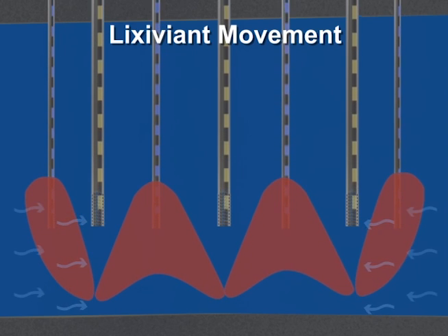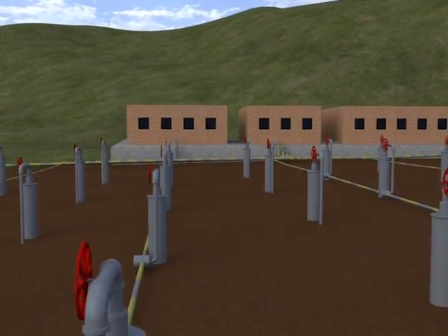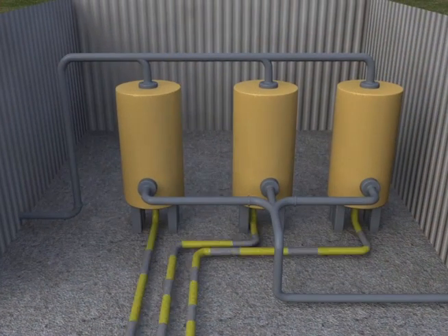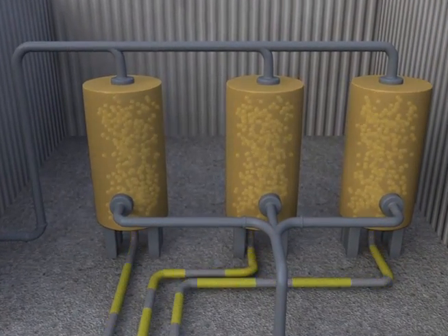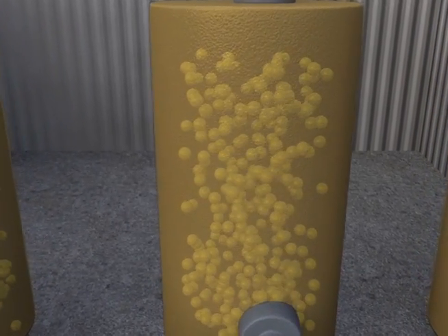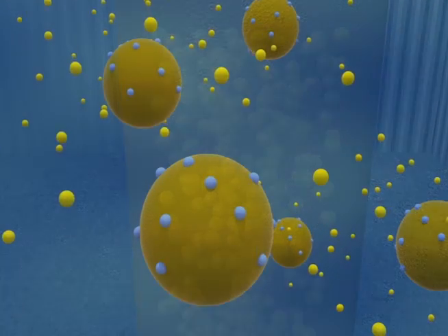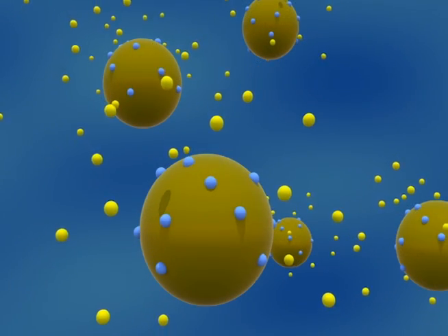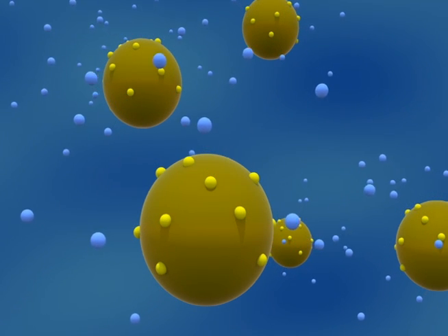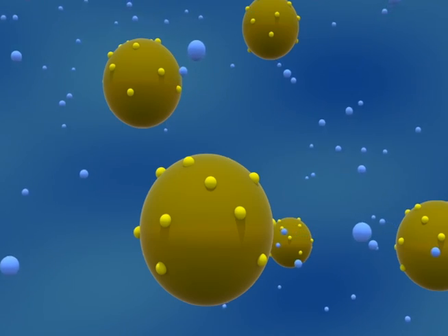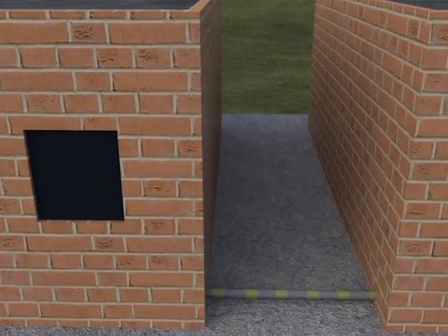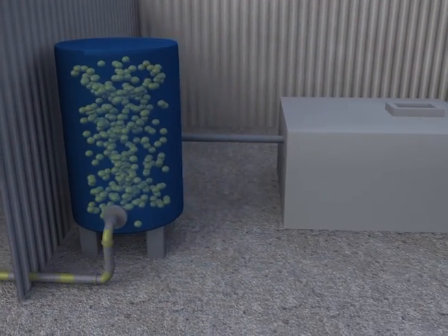The uranium-laden groundwater pumped by the extraction wells is conveyed via pipeline to a processing plant, where it is passed through an ion exchange column containing anionic resin beads that are highly selective to capture the soluble uranium ions. The uranium ions attach to the resin in a process where they displace or exchange with bicarbonate or chloride from the resin. When the resin in a column has captured a sufficient amount of uranium, the resin is transferred to a separate column and the uranium removed by an elution process using a concentrated sodium chloride solution.